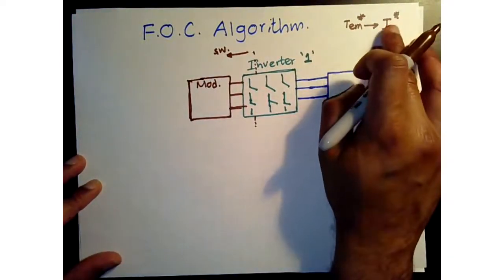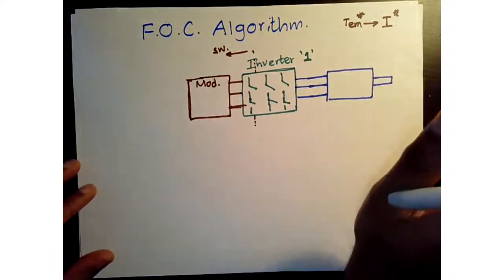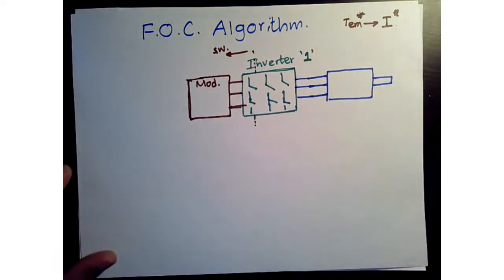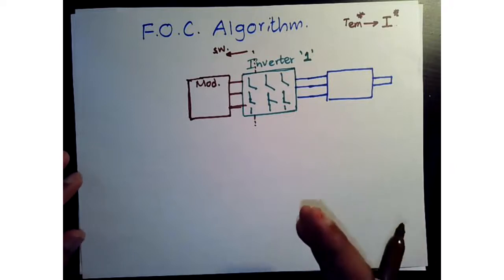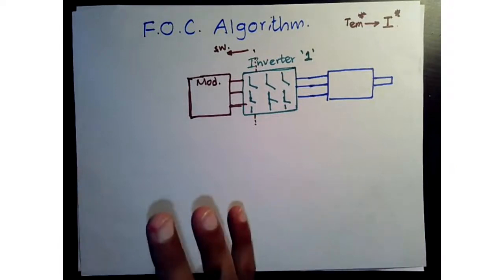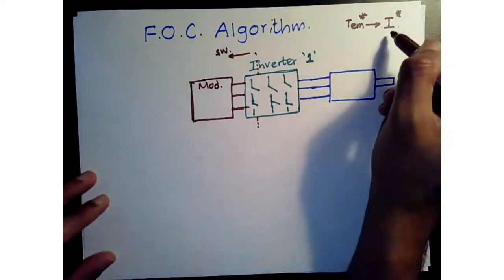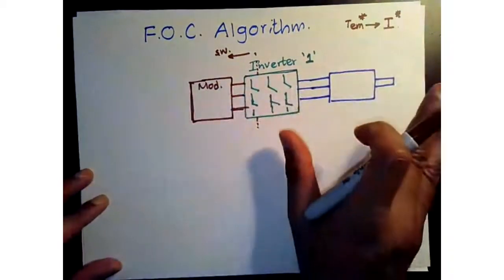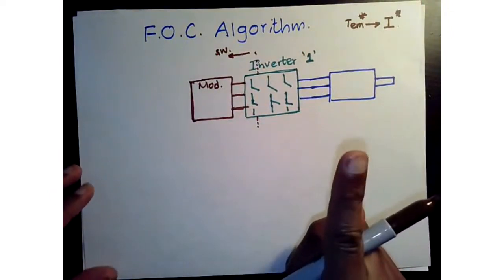In terms of setting the currents, how many currents do we have to control? 3 currents. So Alex is saying we have 3 currents, right? Now, this would have been the way to go back in the days if we didn't have reference frame transformation. With reference frame transformation, we were able to convert those 3 currents to 2 currents, right? So what we are going to do now, instead of going into that sinusoidal domain, we are going to say, hey, we have the position measurement already, right?